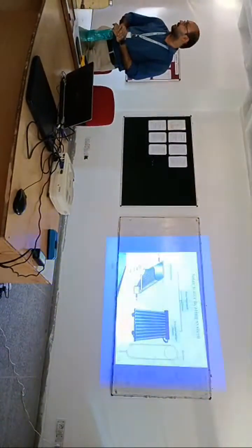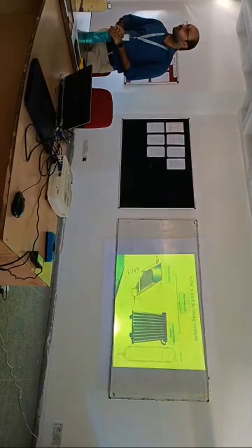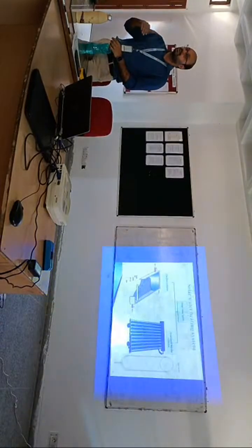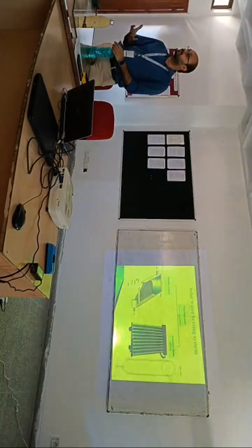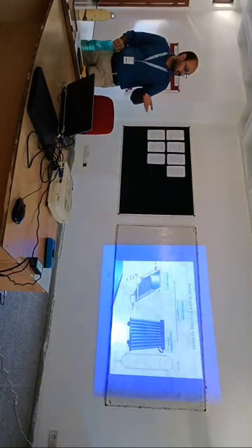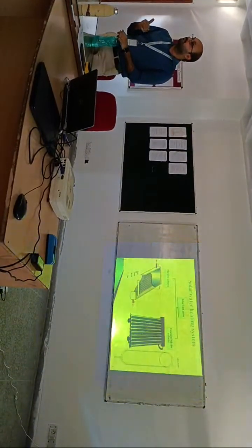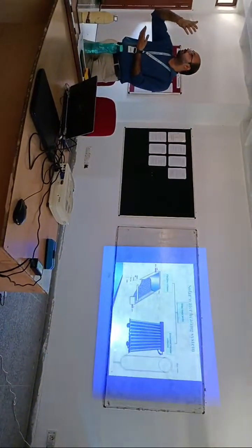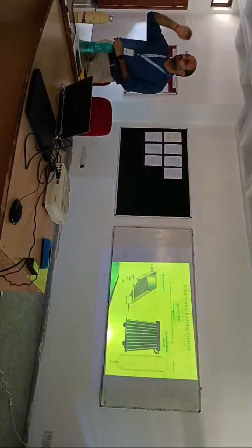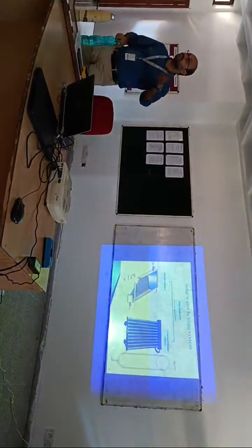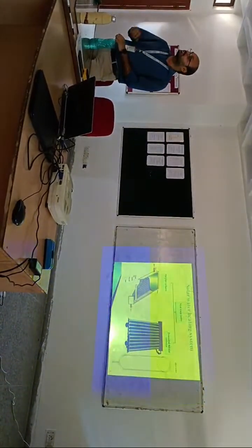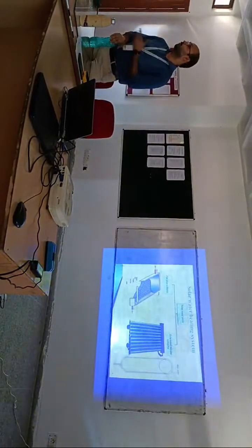The water gets heated, and as the temperature of the water molecules increases, it becomes lighter. It starts rising in the tube, and the place of that lighter water is replaced by the heavier water which is comparatively at a lower temperature. By this process the water circulates in the tube, and this process continues until the water temperature at each and every point of this system becomes the same.